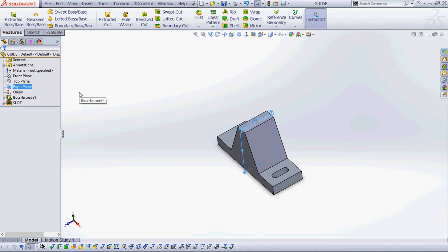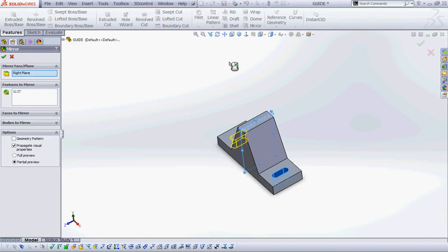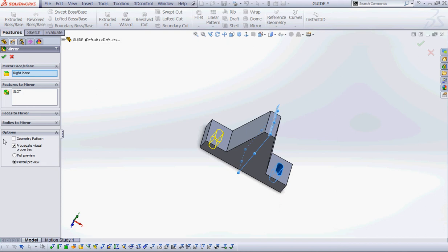And then I'm going to rename that feature slot, and I'm going to save it. Okay, so now it's your turn to place the slot. What do you mean the length of the oval? The slot? The dimensions are on page 1-99, and the slot is 10 millimeters long.